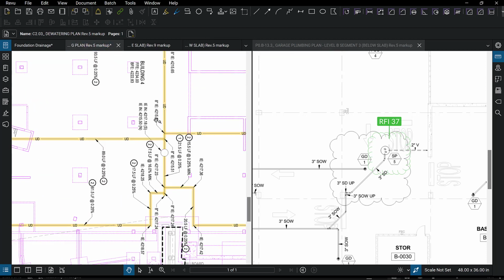So the invert elevation here, that means invert in is on the south, 42, 17, 18. So that's the flow line of the pipe. If you think of the pipe and the inside of the pipe, we'll over communicate a little bit here. That's our pipe. The flow line is where my mouse is right there. That's also the invert elevation.